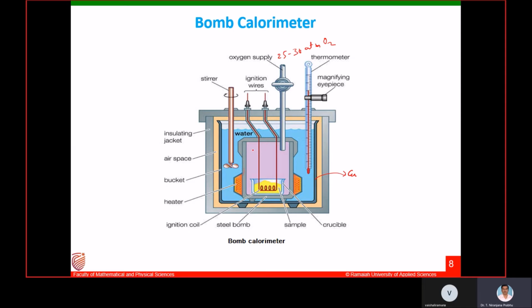They have certain heat content. The products of combustion are cooled to room temperature. Again, they will liberate some amount of heat, that is the latent heat of steam. This heat is also absorbed by water. Now water has absorbed heat liberated during combustion, then heat liberated during condensation of the products. Now again the second temperature is measured.